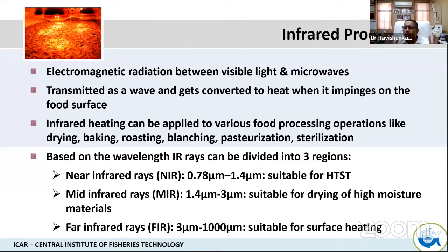So when we are talking of dry fish, conventional drying techniques have to be replaced. We are talking of hybrid dryers, solar dryers, infrared. We are also working on that. The advantage in infrared is very, very fast drying. Earlier, in the conventional drying, if you are using an electrical heater, there is case hardening, so that is affecting the quality. Whereas with infrared, we have seen the quality of the dry products is better.